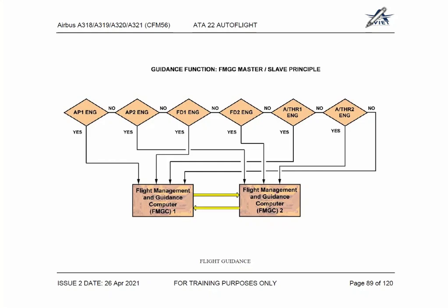The only thing is, both autopilots can be engaged only when the aircraft is in descent, approach. Once the approach button is pressed, only then can they engage the second autopilot. When the second autopilot is engaged, number 1 will be master and number 2 will be standby.